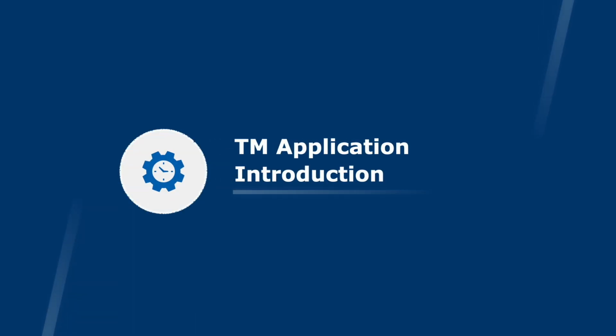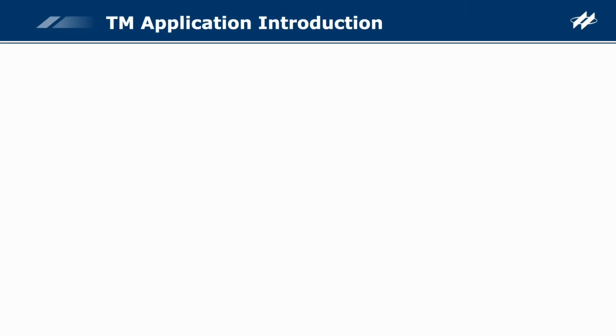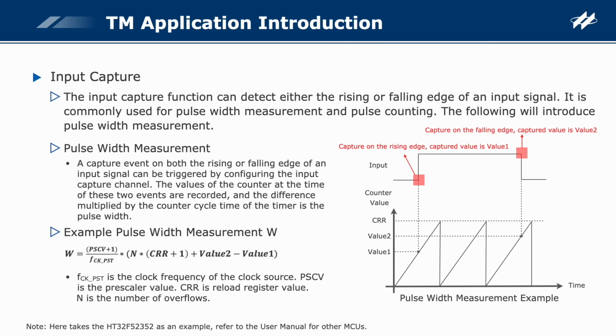TM application introduction. The input capture function can capture either the rising or falling edge of an input signal. It is commonly used for pulse width measurement and pulse counting. The following will introduce pulse width measurement.